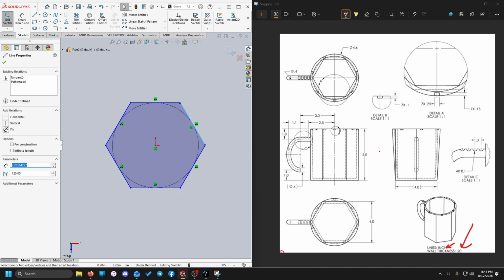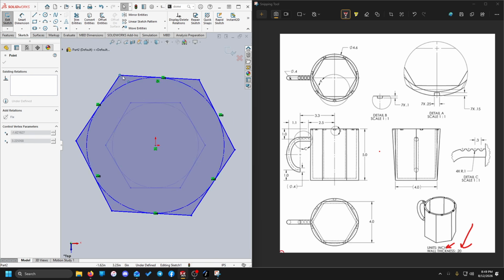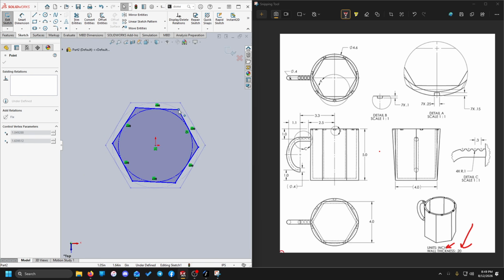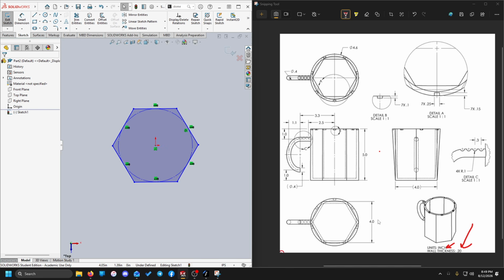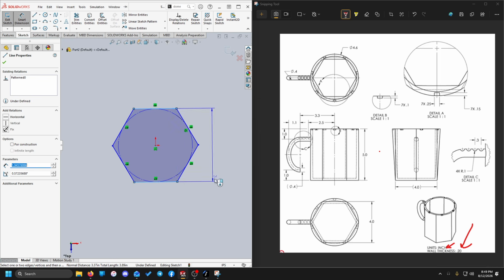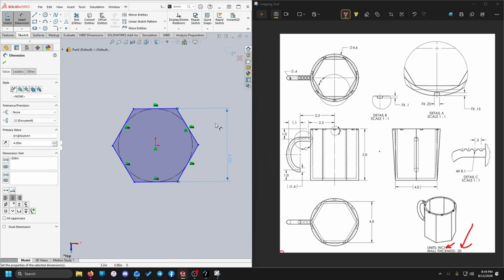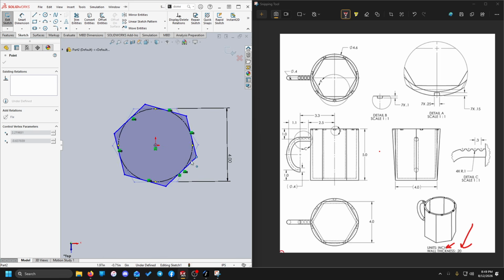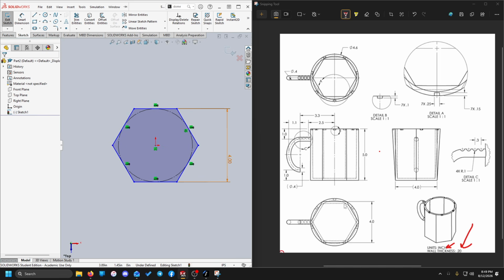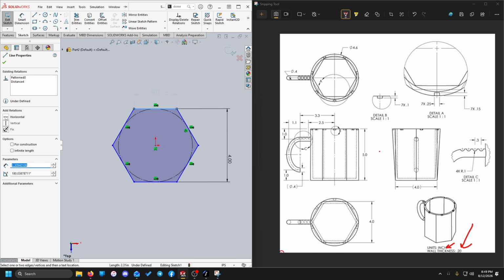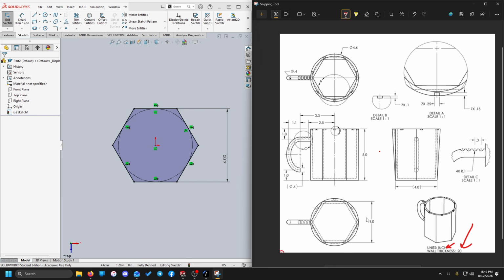So that gives us a shape to work with, but it can still rotate freely, and we don't have anything for its size. Size is easy enough. We have a dimension specifying that the distance from the top edge to the bottom edge is 4 units. Now to get its orientation down, we can see that we've sort of got one straight edge on the top of our object, so I'll just grab one of these, set it to horizontal, and that gets us fully defined.